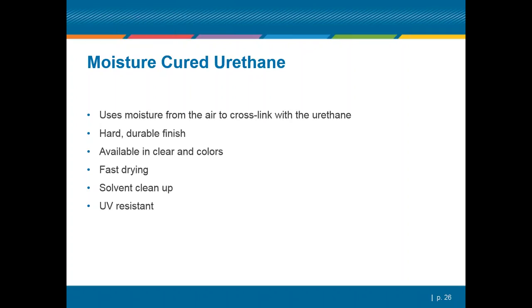The cross-linking aspect of it is really kind of unique in that it doesn't take a catalyst per se like other cross-link products, but actually picks up moisture from the air. That raises the question, if I'm in a very arid environment without a lot of humidity? Sometimes you have to actually mist-coat these with water to get them to cure.